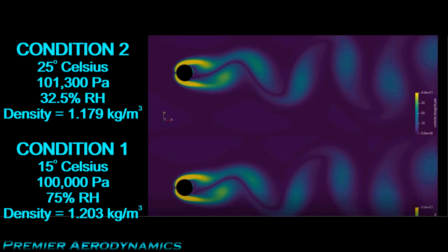So that's a massive problem because you might think, okay, that's 1% error in the velocity, but if you think about the change in the flow physics, it has a big effect. For example, the Reynolds number will be different by about 3 or 4%. And so, for example, if you're testing, let's say, a wing at a Reynolds number of 100,000 or so, that's right in the prime range for a laminar separation bubble to form.